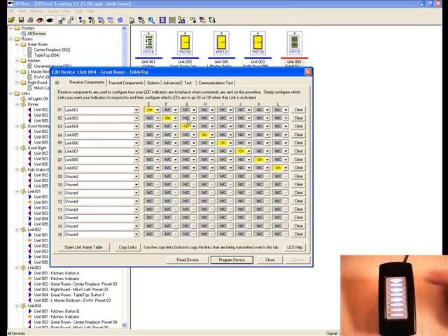Now you notice when I push the E button, the other LED lights stayed on. So if I want to reactivate one of those scenes, I need to currently turn that scene off and then reactivate the scene. To fix that, I can tell the E button that when I push you, I want all the other buttons to turn off, or any combination you wish.